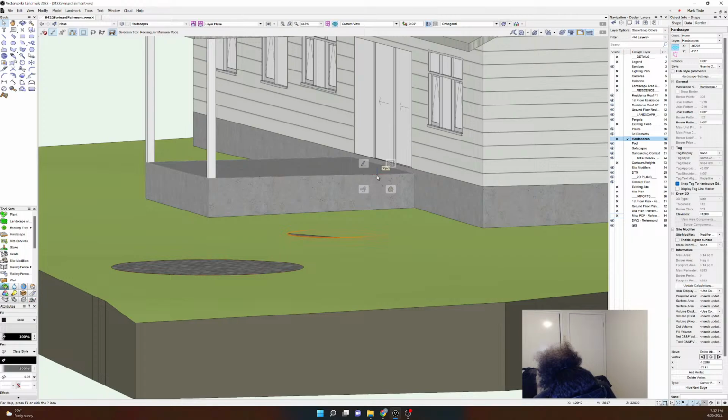It'd be what, 770, but then we'll also have a 40 mil paver and some glue on it, so it'll be about 810. But that's fine because we won't need a handrail under building codes. We won't need to worry about a handrail along here, which is a pretty key part of the design, was making sure we didn't need a handrail. So long story short, I'm happy with 31200 there, and I'm also going to change this to modified top, which